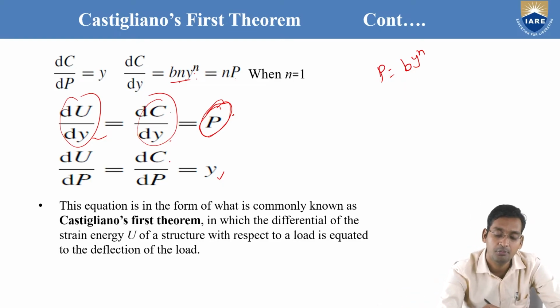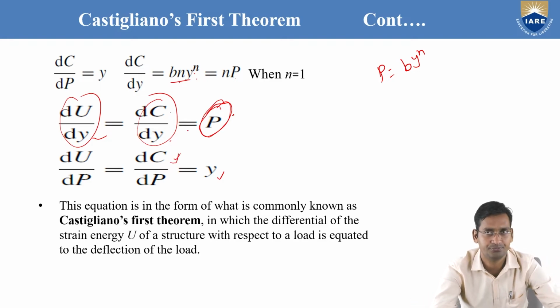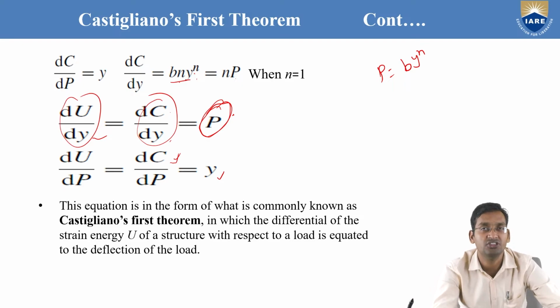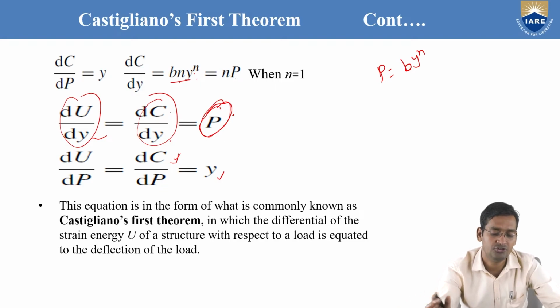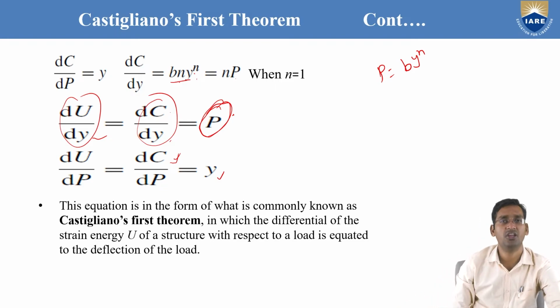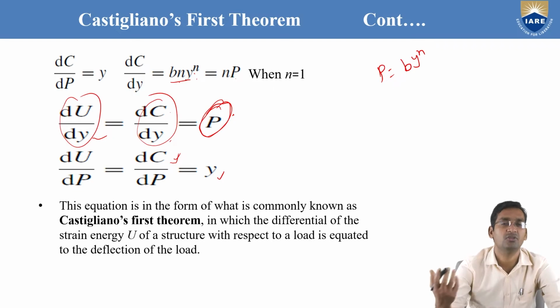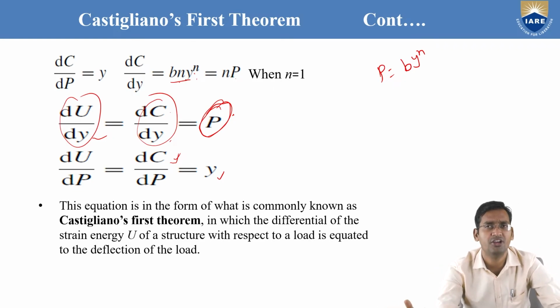So we find it using the complementary energy method. Since the complementary energy with respect to a small change in deflection or a small force comes out the same, we can use the same for the strain energy also, and hence we can find the amount of deflection because of the applied load.